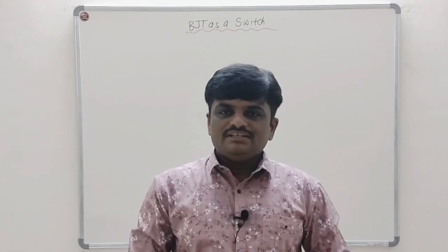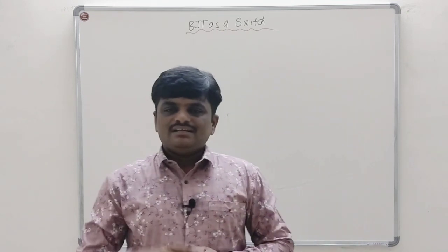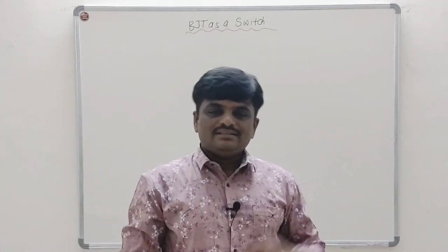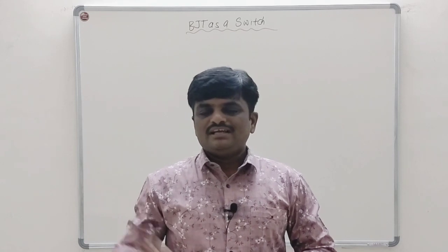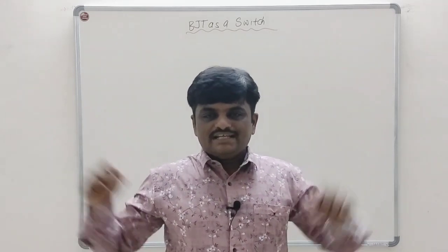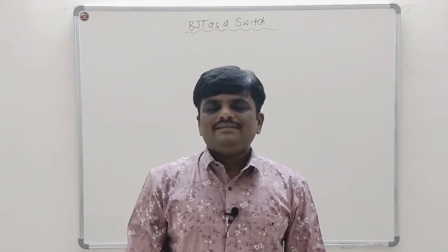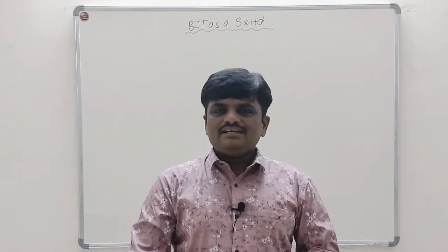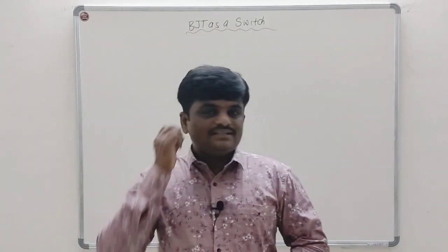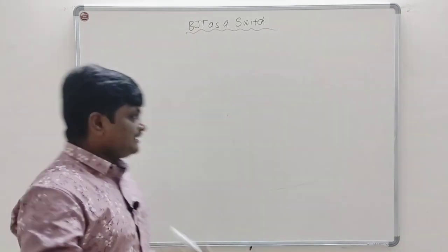In the common emitter configuration, we have seen the circuit diagram. There, the emitter is common, the base is the input terminal, and the collector is the output terminal, and with the help of two DC supplies, one at the input side and the second at the output side, we have done the proper biasing of that common emitter configuration. Now I will draw a modified, simple circuit so that you will come to know how this BJT can be used as a switch. So see the circuit first.